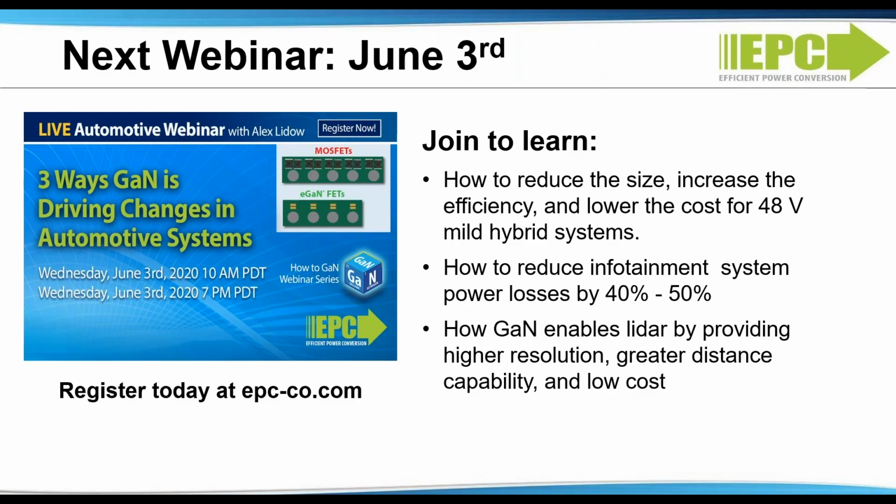The gate to source tends to fail through a dielectric failure between the gate metal and the field plate, and we have pictures of that. In drain to source, the failure mechanism, if you go to much higher voltages, tends to be an increase in on resistance. This is dynamic on resistance, but as I said, we've designed it so that it doesn't kick in if you stay inside our rated datasheet limits.